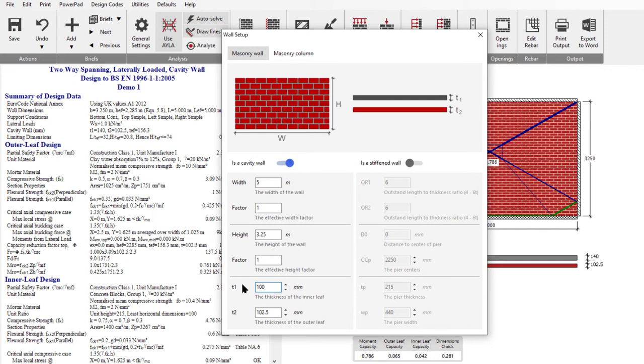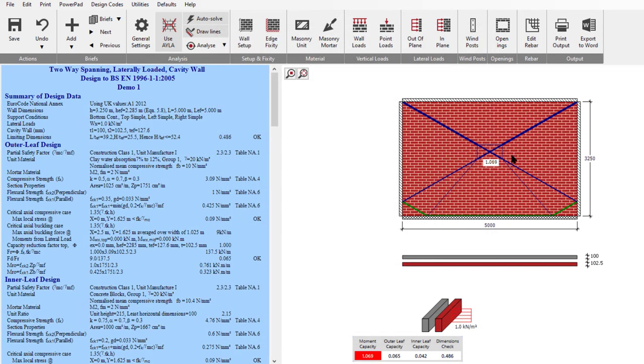The architect is selling it per square meter or square foot, and the client, so we really don't want to suddenly lose all that area of retail or housing space because it costs money. So the only other solution is to start and reinforce this. We can reinforce our wall in one of two ways, or in both ways in fact.